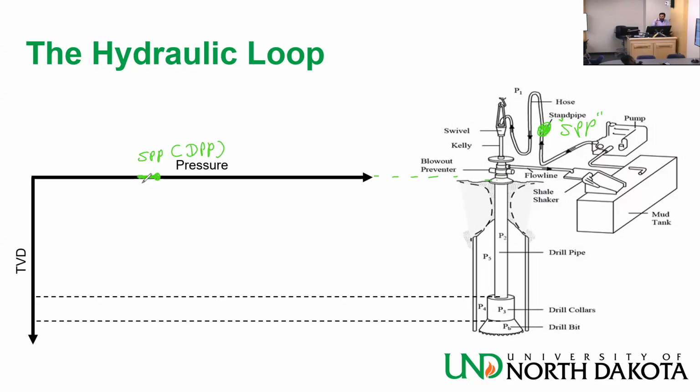But I'm at about the same depth. I ignore how much depth I gain. Then I'm here. I'm moving into the same conduit, and I'm going deeper. That means I have more weight above me, but I'm also losing pressure to friction. Overall, I gain pressure. The value becomes bigger because I have more fluid above me than the pressure that I'm losing moving down there. So let's just draw it like this.